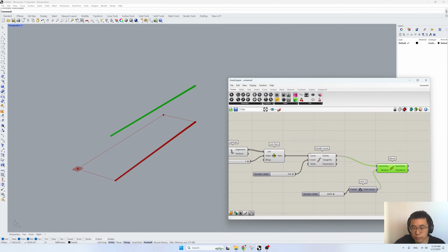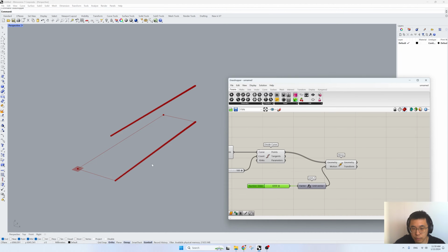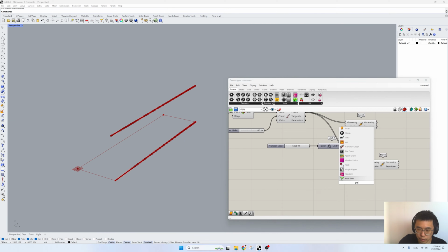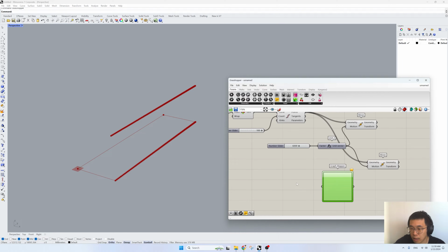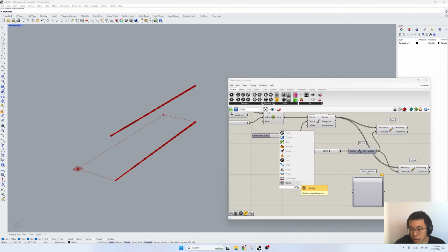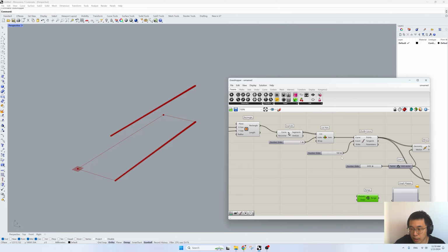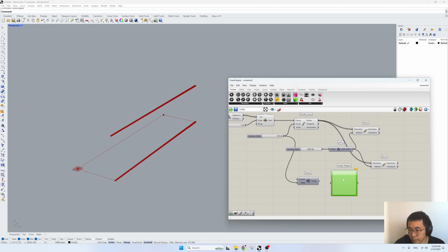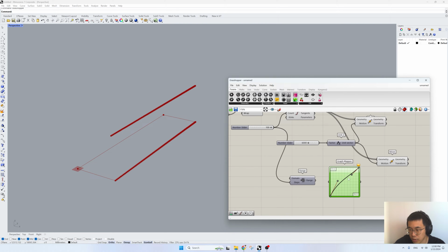That's the bottom fin. We're going to have a bit of a fancy bottom. So what we're going to do, we're going to copy this move here, over here, and we're going to use a graph. It's called graph mapper. We create a range of numbers. The domain will be 0 to 1. Then step will be, because we have 100, so it will be 100. So range, we can get 101 numbers. Then right click, we're going to choose Bezier. Going to change the parameter a little bit, something like that.